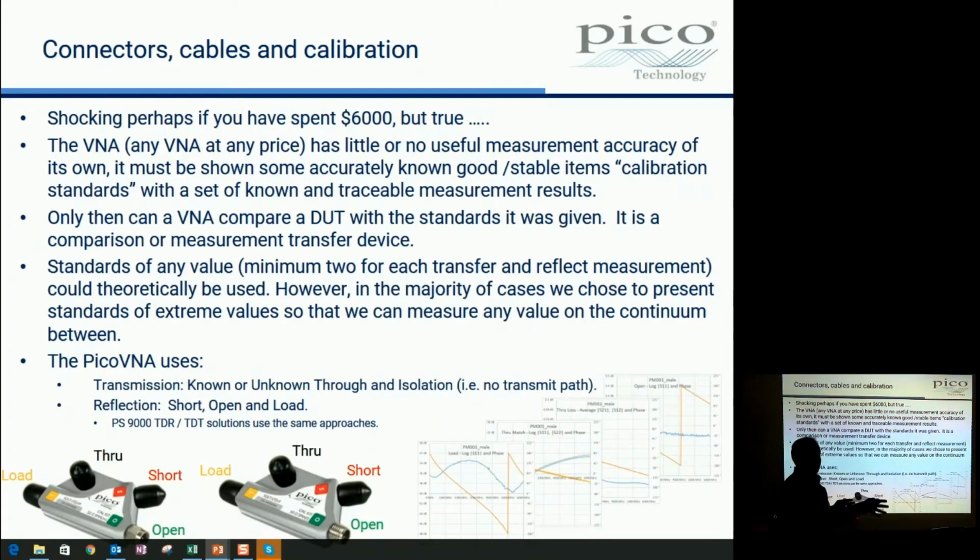We're really focused on a particular impedance, Z0, the characteristic impedance of the VNA and all the measurements that we're going to make, 50 ohms. So it's handy just to have a load, essential actually. We need a precision measurement of what precisely 50 ohm looks like. Well, no, not precisely, but pretty close, provided with a data set that says how close we are.